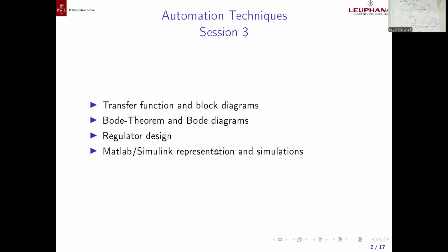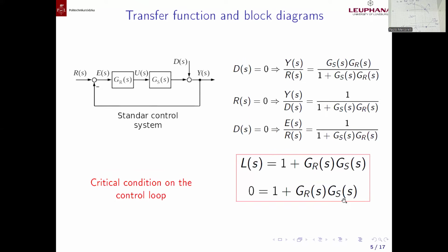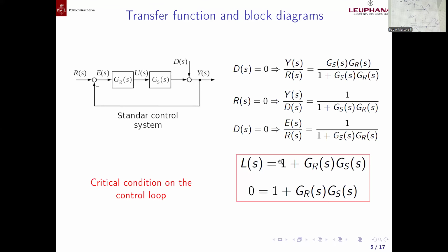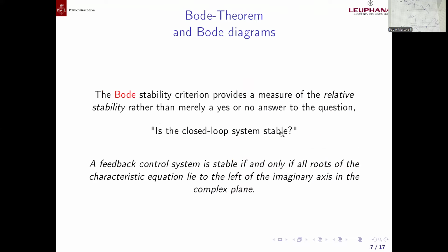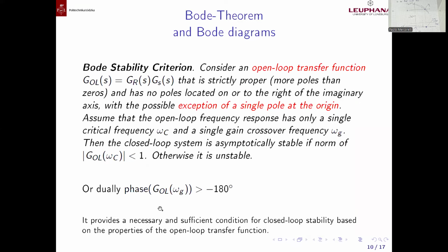It's really easy. You remember this was the discussion that this complex expression can be equivalently written more concretely as two real conditions, this here and this here. Now the question is, when do both happen together? When both happen together, we have the critical situation that we have a 0 in the denominator. Do you remember this analysis: omega g and the phase at omega g.